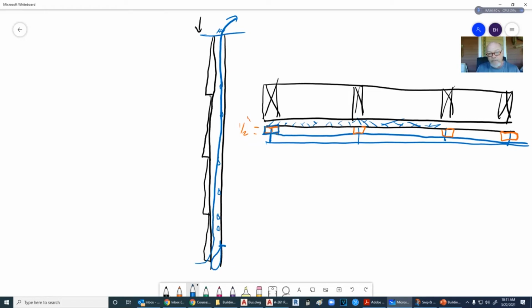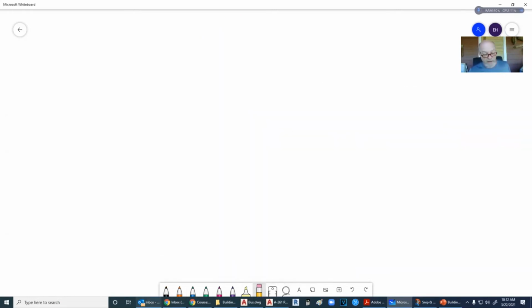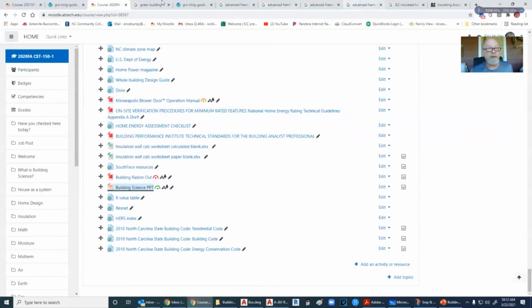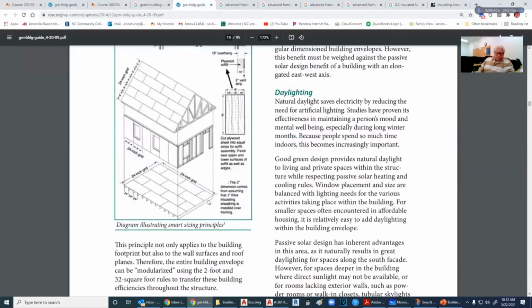And me personally, I have found that nailing them by hand is the best way rather than a nail gun, because a nail gun is going to shoot it in there and they don't give a flip about it. And so I've just had a lot of problems with them busting with a nail gun. What about staples, like the thin, what they call crown staples? Yeah, you could do crown staples. That would probably work better. I didn't think about it, only because I don't have one. I don't have a crown stapler. Oh, that's a good investment. Yeah, it is.